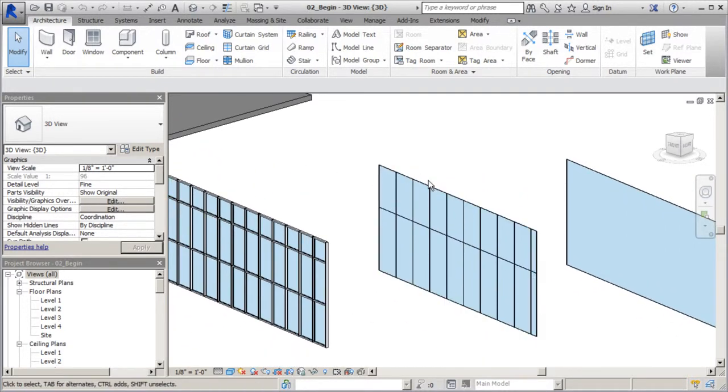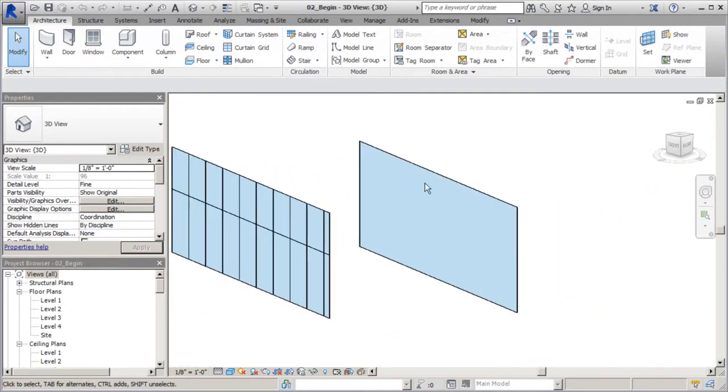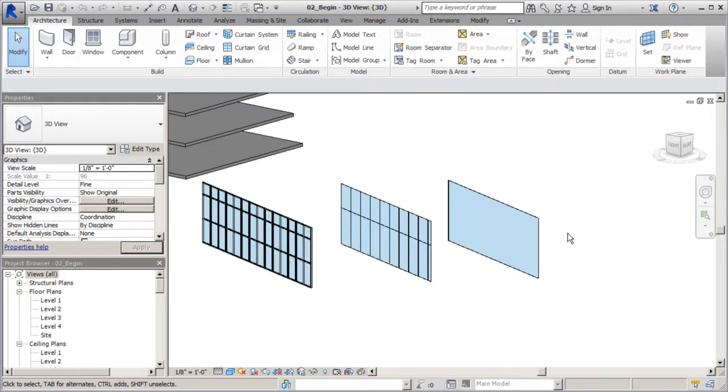So if I go to the second option here and I scroll in just a little bit, you see we definitely have glass. That's one element we have, but we also have our grid lines. So those are the main two that this one has. We can still manipulate and move the grid lines however we want to, and then attach mullions to them. Now this system here has only glass, and this one actually provides us with the most flexibility in terms of how we want to lay things out. So you can look at this as a blank slate or a blank canvas, and you can lay out your grid lines and then attach mullions to them. So that's going to be the main difference between the three.